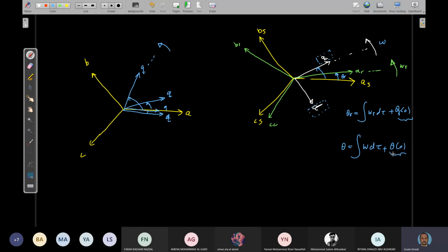Now, physically, can I put it anywhere? No, because I don't know exactly where the rotor position is or where the rotor flux is. If I need to align the reference frame with the rotor flux, I don't know actually where the rotor flux is. But simply, in the second stage, I need a controller in order to make sure that I'm matching the frame. For example, do you remember that in the transformation we are using a scaling factor, which was 3/2, for example?